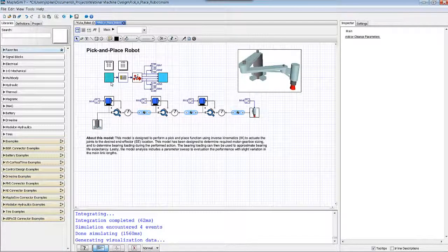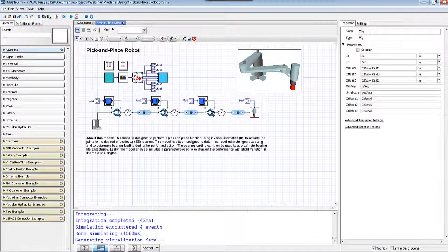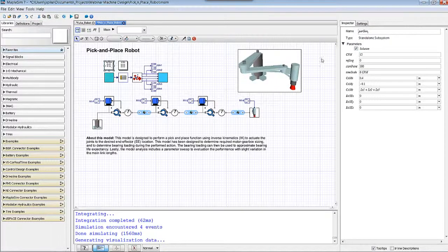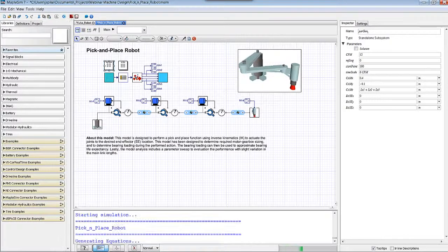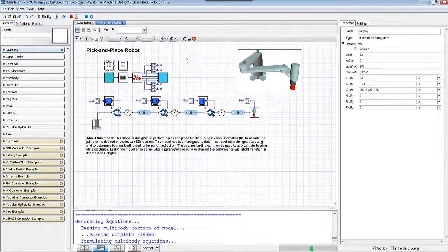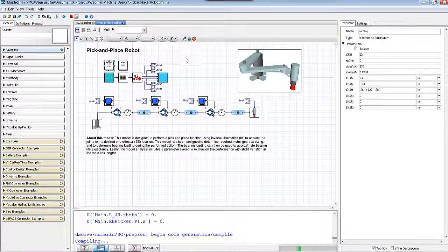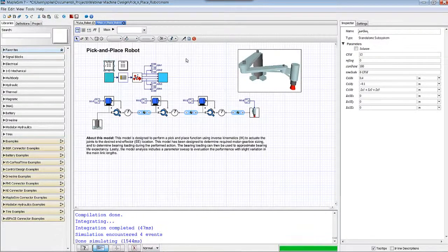The model includes inverse kinematics, which have been parametrically specified to allow for a link length for L1 and L2, as well as a different solution type. We can vary our solution type easily by toggling the toggle button and rerunning the simulation. This will allow the mechanism to be simulated with the second set of solution results that can be obtained with the SCARA-inspired robot pick-and-place mechanism we have here.